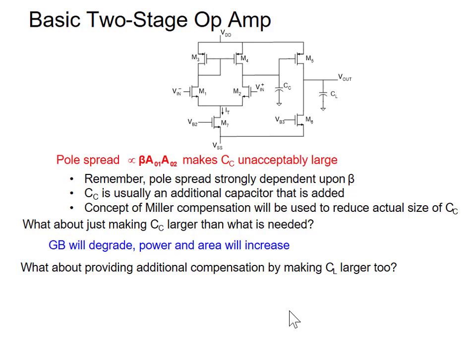I say if they're either parallel or in series, they will be equivalent to one capacitor. Yeah, I understand. So we're going to put more capacitance on here, an extra capacitor on here. It won't change the phase model. Okay. So it makes the area a little bit bigger. Power might go up a little bit, but outside that, we're all right. It doesn't change it or makes it better. Remember, putting capacitor on either node helps it.